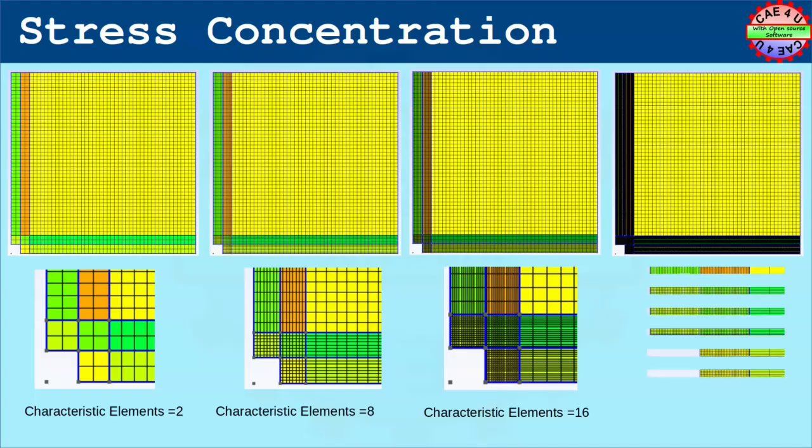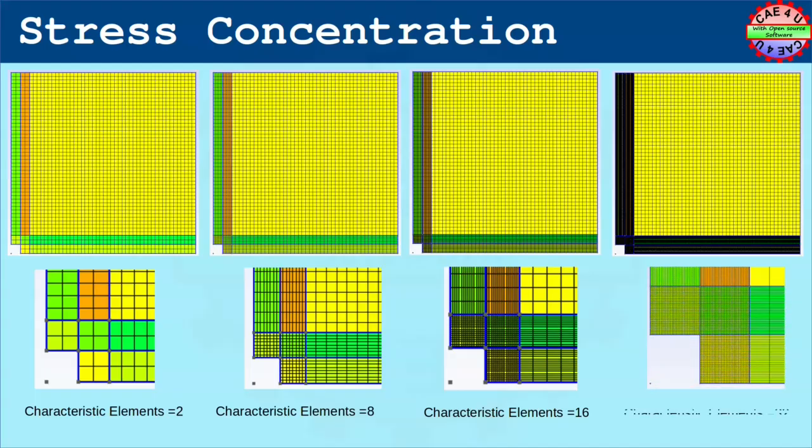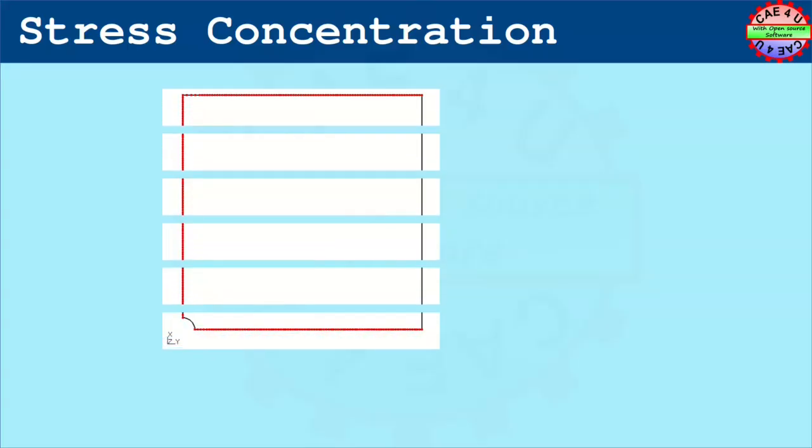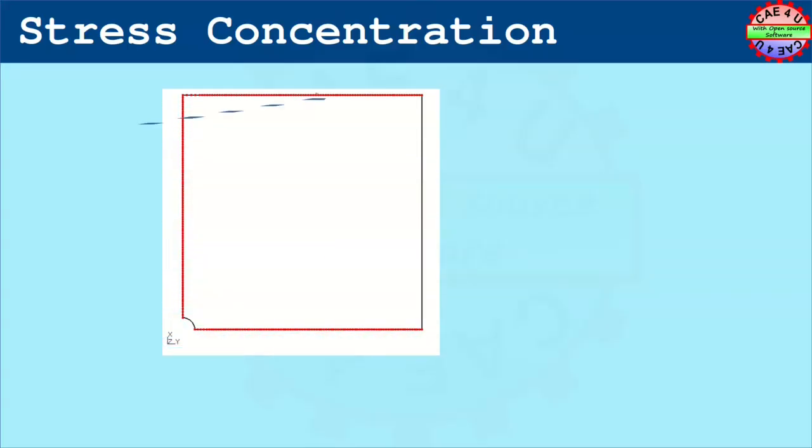Higher order quad element was used for this simulation for better accuracy and computational efficiency. The geometry and mesh was created using GMSH. Let us look into the boundary conditions and the loading conditions, which will be used for the simulation.